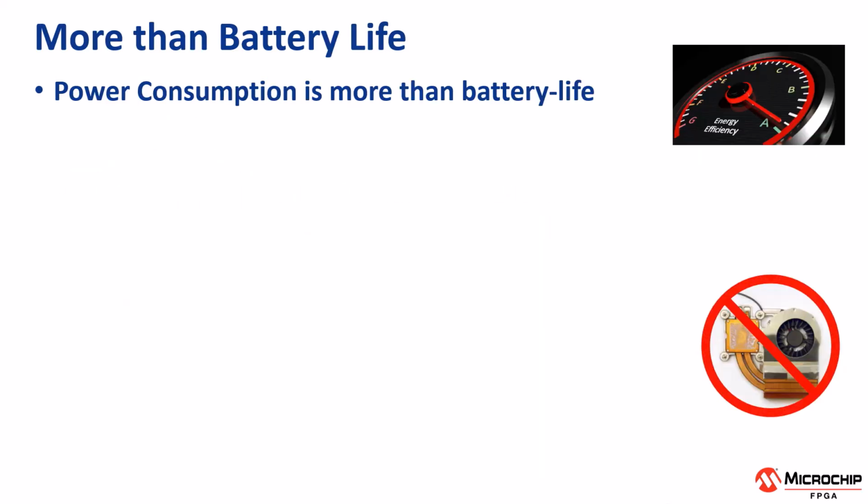Lower power consumption has positive system implications that go beyond battery life. Lower power consumption results in lower self-heating, so the device will remain cooler. This is important because semiconductor devices are specified for a specific operating range with a maximum junction temperature of typically 85 degrees C, 100 degrees C, or 125 degrees C. At this temperature, all timings inside the device are still guaranteed. If the temperature is exceeded, functional failures in the design might occur.